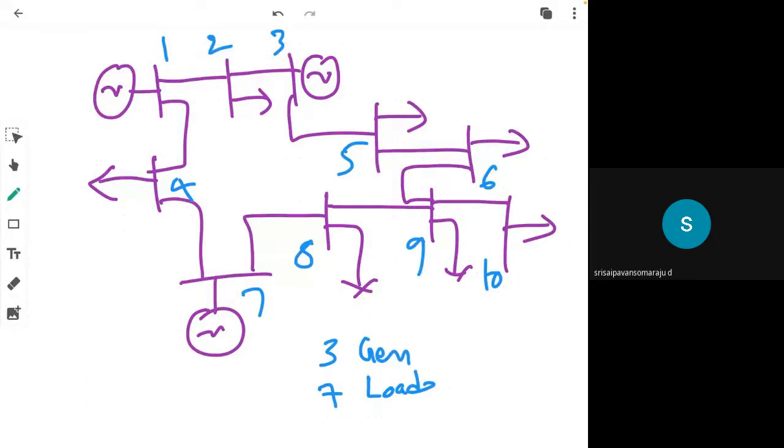So in an interconnected system, if you decrease the current through all the lines by placing the compensators in distinct places, you can decrease the current through the transmission network, and hence overall loss can be minimized and reactive power requirement can be minimized. Many advantages.